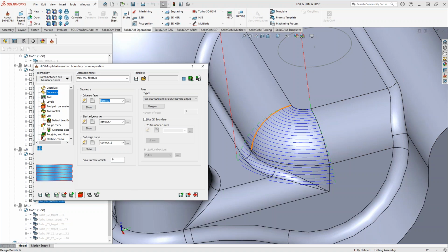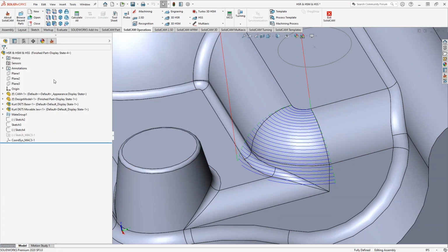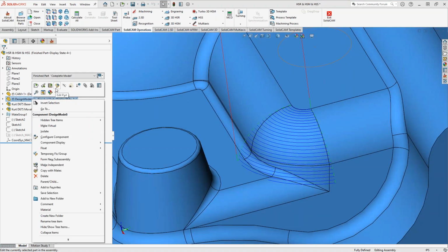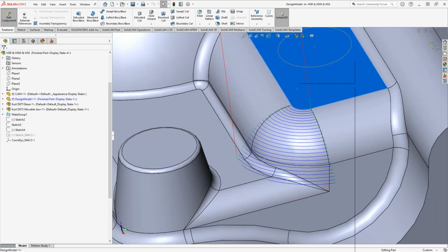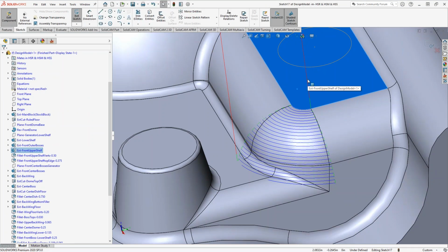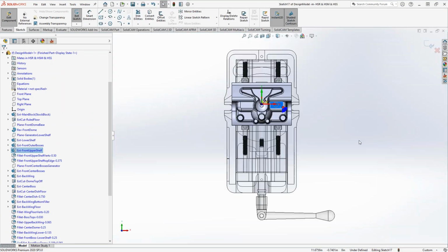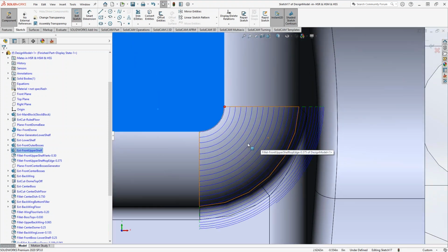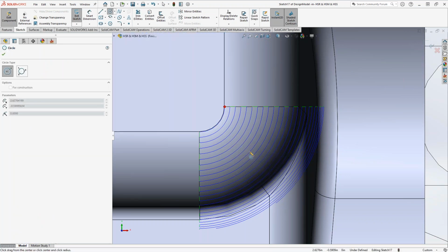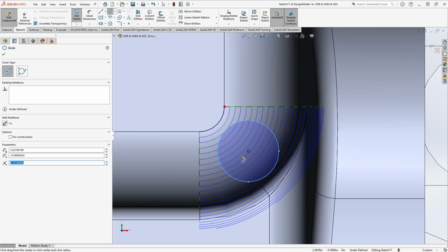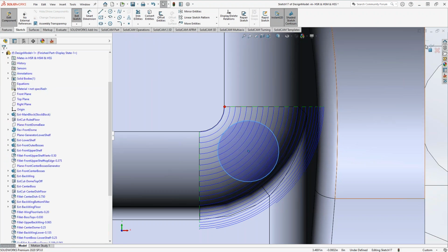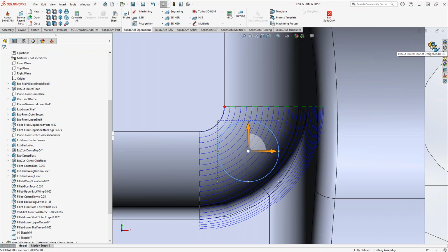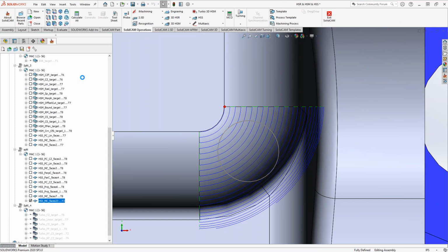All right, so let's close this guy down and let's go and add a sketch. I'm going to add a sketch to our part model. Put a sketch on that plane there. Let's get our top view. So let's say, like Kevin said, maybe there's a little bit of a nick there. We filled it in with some weld or something like that. Now we have to refinish it. Grab a circle, and I'll make a circle probably just as big as the part, but maybe just that one circle shape there. All right, there we go. Exit out of there. Now we have a nice two-dimensional circle there.